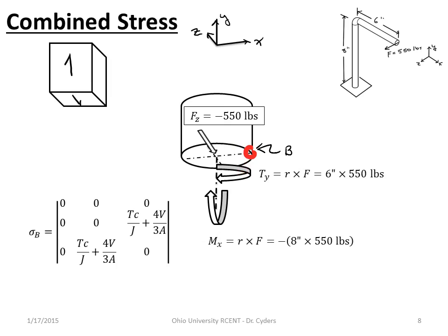Of course, if we looked at the opposite point from point B, we would have one minus the other, so they'd be kind of canceling. So point B is going to be greater than the opposite side of the cross-section from it, whereas with the bending moment, that's not exactly the case because they're different stresses. But because we're combining those shear stresses in the same direction, we will have a higher shear stress at point B than we will for that point across the cross-section.